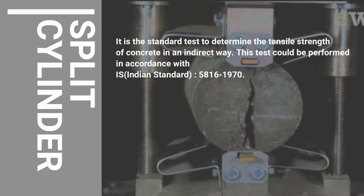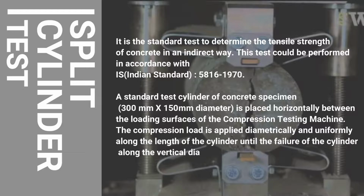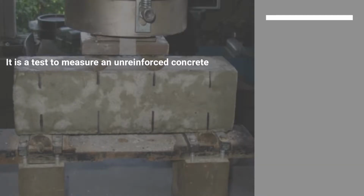First is the split cylinder test. It is the standard test to determine the tensile strength of concrete in an indirect way. This test could be performed in accordance with IS Indian Standard 5816-1970. A standard test cylinder of concrete specimen 300 mm by 150 mm in diameter is placed horizontally between the loading surfaces of the compression testing machine. The compression load is applied diametrically and uniformly along the length of the cylinder until the failure of the cylinder along the vertical diameter.